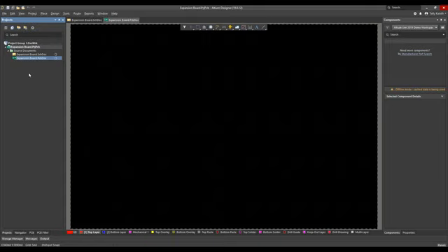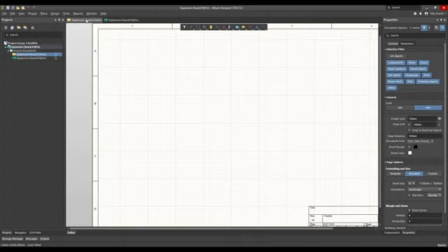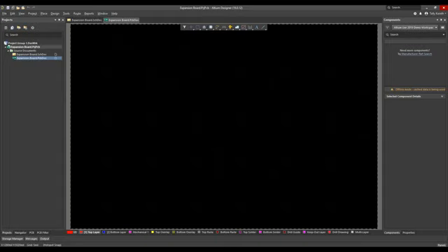Note, the project does not contain the actual files, only links and their locations. Clicking on either the entry in the Projects panel or on the tab above the active window will switch the view to that file. Here we click on the Schematic tab to change the schematic to the active window. Clicking on the PCB in the Project panel will make the PCB the active window. To open a file not already opened, double-clicking it in the Project panel will open it.